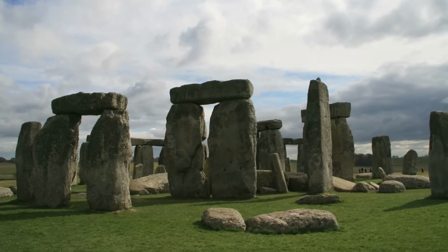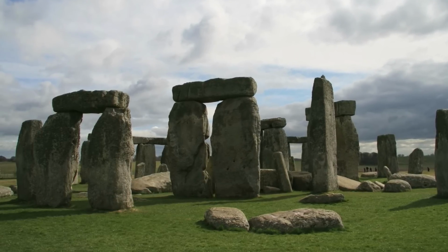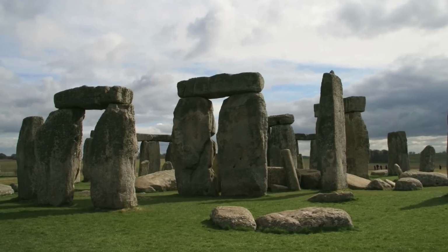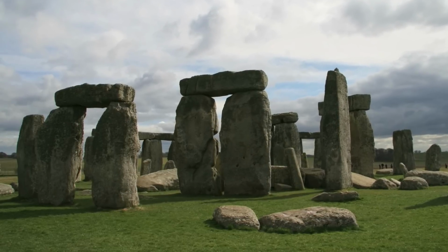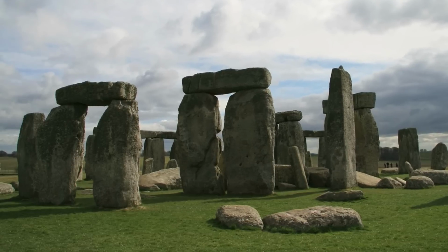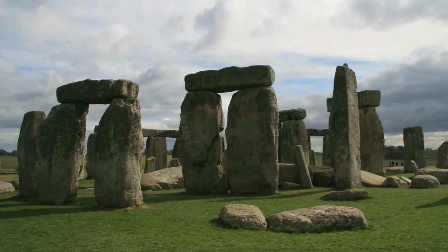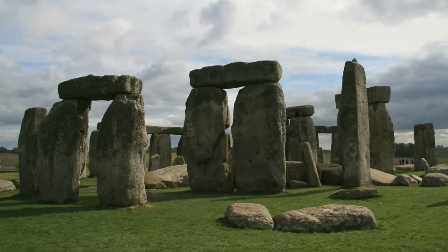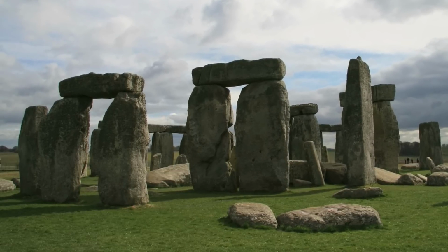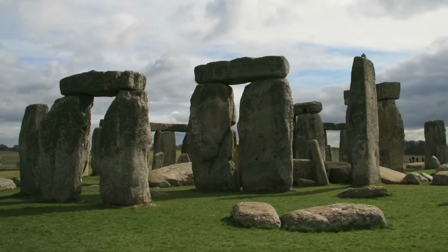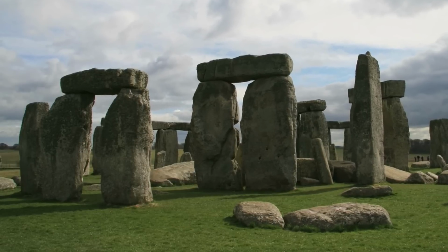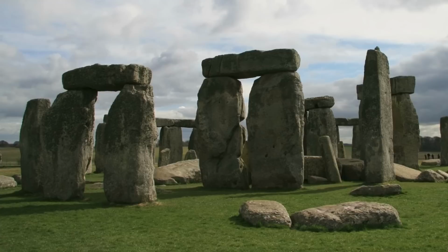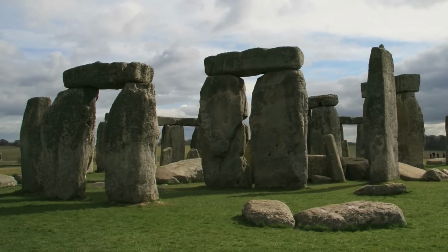One example of a pre-industrial revolution structure is Stonehenge, and I use this example of Stonehenge to show essentially how far stone can span. In Stonehenge, the unsupported length of that beam, that horizontal member, is on the order of 10 feet. Stone is not very strong in tension, and this beam on the bottom surface is experiencing tension. We're going to learn more about beams and tension in later lectures, but for now, know that, again, stone does not carry very large tensile forces. It's not strong in tension.